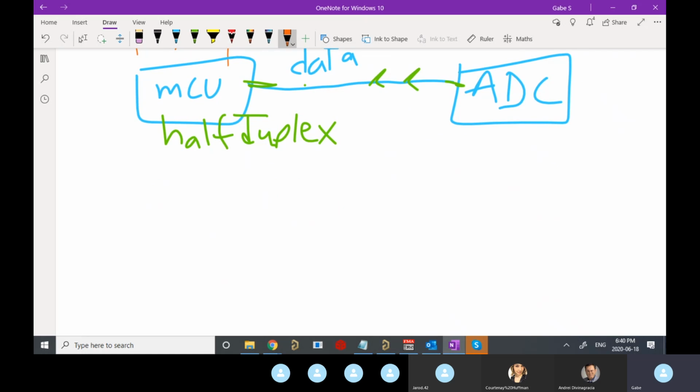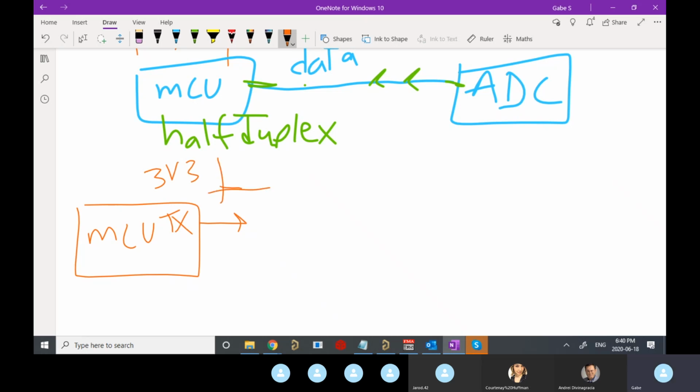So what does a little data packet actually look like, right? If I had a microcontroller, let's look at the TX line. So we're sending data, right? And what it actually looks like is something like this. Let's say our logic level is 3v3, right? We know we can send a 0 or a 1 or a 0 or a 1. And that would be 0 volts and 3.3 volts, right? This 3v3 is just notation for 3.3 volts.